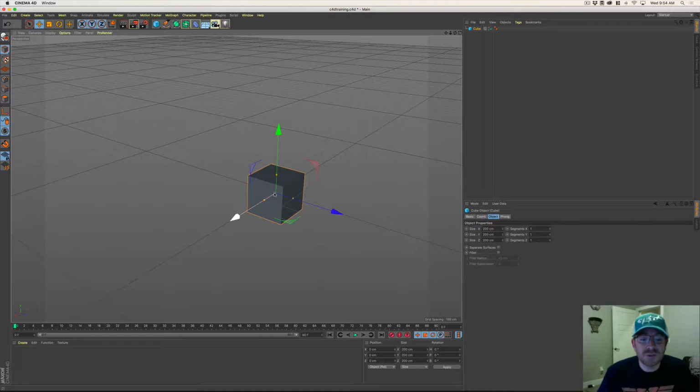First of all, you're seeing ways to move your object if you have your move tool. So the move tool is right here. So go ahead and select that. Or you can press E on your keyboard. It's a good shortcut to get down. You can move this in 3 dimensions. You can move it vertically. So if you grab the screen arrow and move it up, you can move it in the Z direction, that's the blue one, or the X direction, that's the red one.